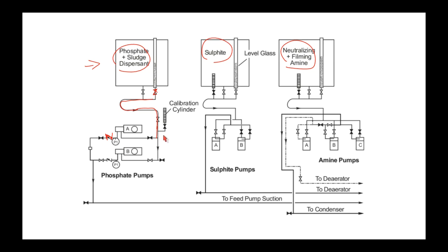Okay, so for those who don't know what a pump drawdown is, here's our chemical feed pump. Maybe it's got a little adjustment knob, or maybe the control room is going to change the pump stroke or the pump speed. But anyway, somebody somewhere has done a test and says, oh, we need more phosphate. Okay, how much more do we need? Well, right now, our current feed rate is 50 milliliters per minute, and I want it to be 60 milliliters per minute.